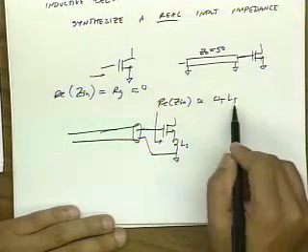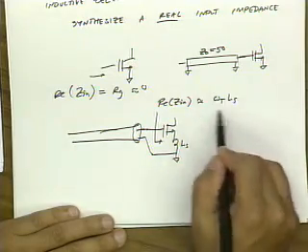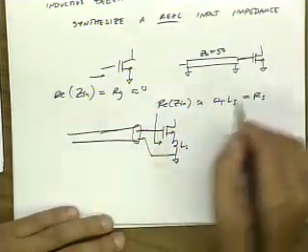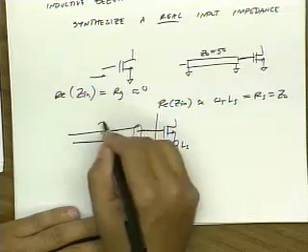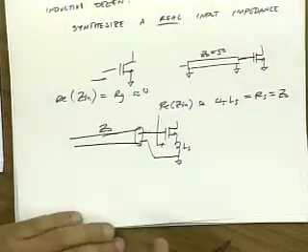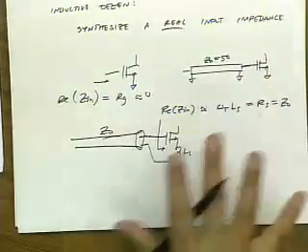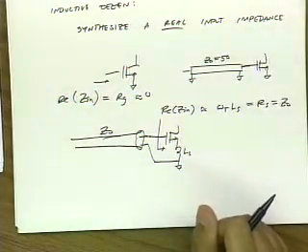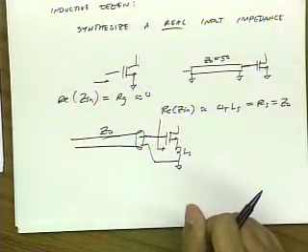So I can make LS large enough so that this product is exactly equal to RS, or let's say Z0 in the case of a transmission line. Now we're going to talk more about designing amplifiers that provide an input match, but this is a preview of what we're going to do.